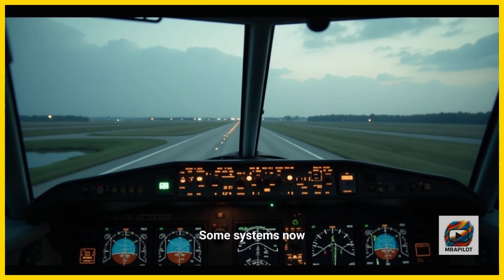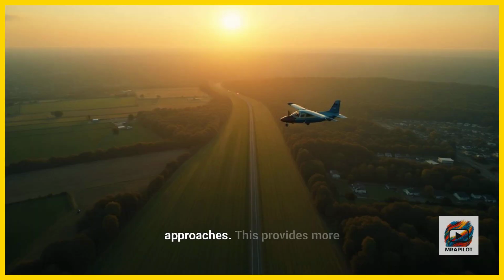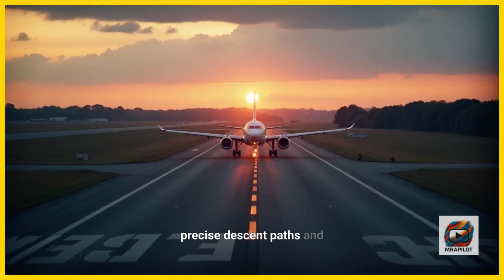Some systems now integrate BaroVNAV, a system that uses barometric data to guide vertical paths during RNAV approaches. This provides more precise descent paths and can even allow non-precision approaches without traditional ground-based aids.